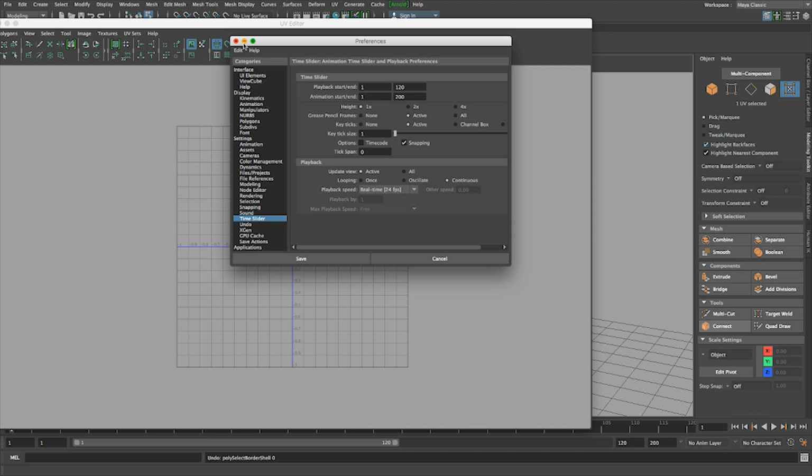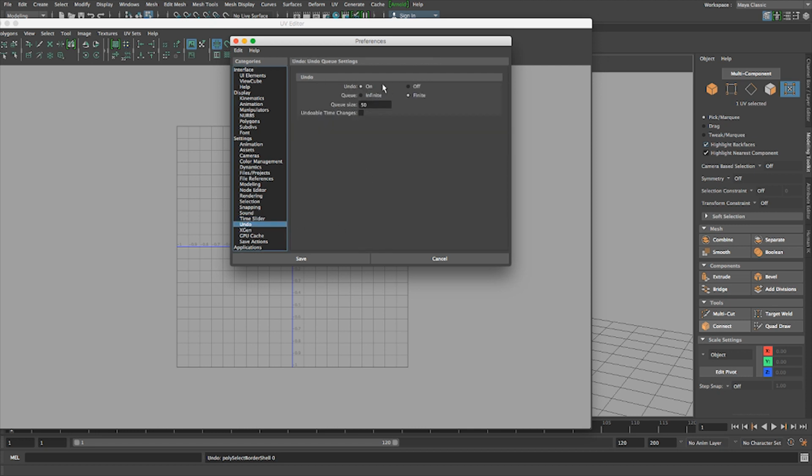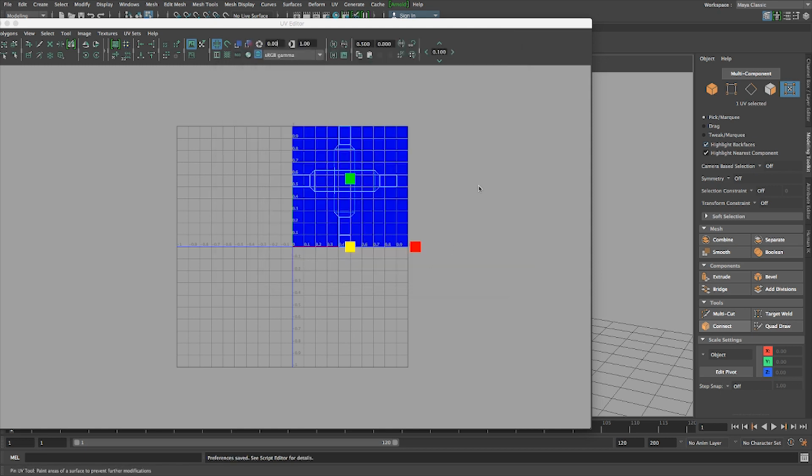So here I can change, and it's broken down. If I go to my undo, which is here towards the bottom, you see undo is 50 times. You can also say infinite. That means forever. It won't change. The problem with this undo is it really keeps memory, and then it can stall the computer. The solution we have for this, I'm not changing mine, I like this finite 50. What we can do is,